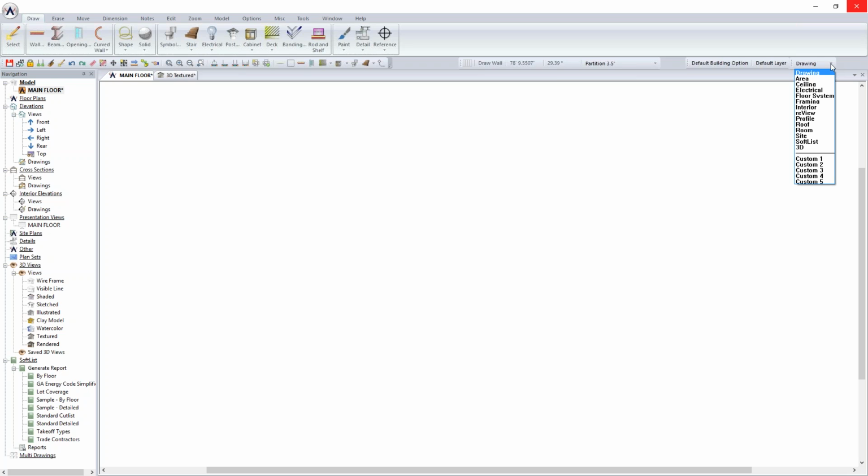And in essence, if there was a change to that floor plan, I would actually need to pull up possibly as many as 3 or 4 or 5 sheets of vellum and go in and make that change 5 times, so to speak. In this case, what we do is we store everything as part of the main floor plan drawing. And then what we do is we view it through different modes. So when I'm drawing walls, windows, dimensions, I do that inside drawing mode. And when I want to put the roof on, I change modes.